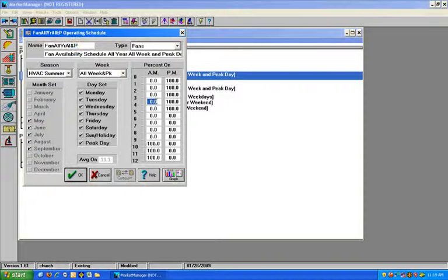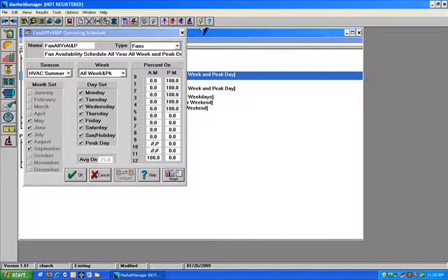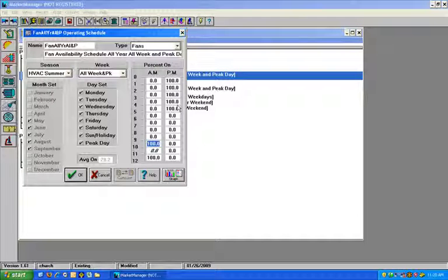Again, if you wanted to do things quick, you just type in a number and then you press tab, number, tab, number, tab. If you wanted to know the default, here, let me put some of these numbers in and then see how they're italic because they're not default. You can press F9 and then tab to go to the next field. Okay, so F9 is the same as doing this thing. It's just a lot faster.